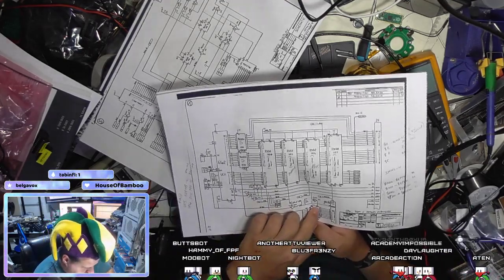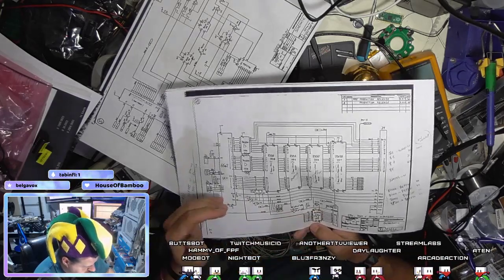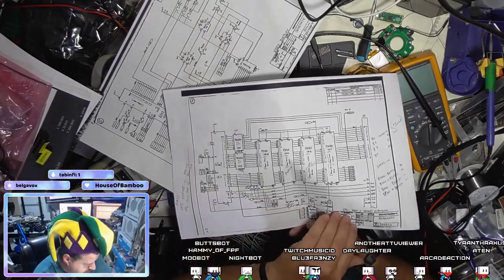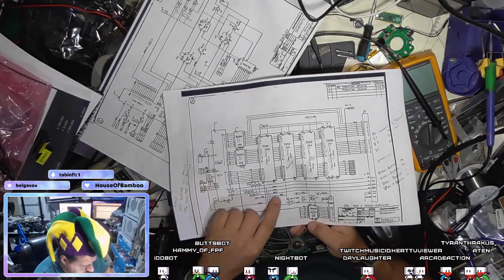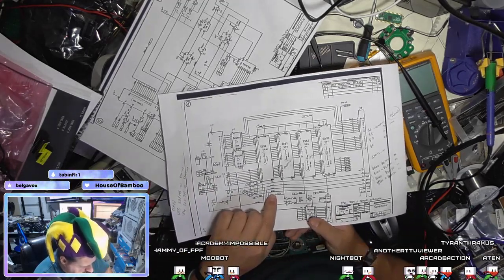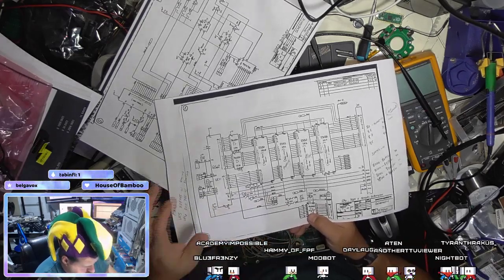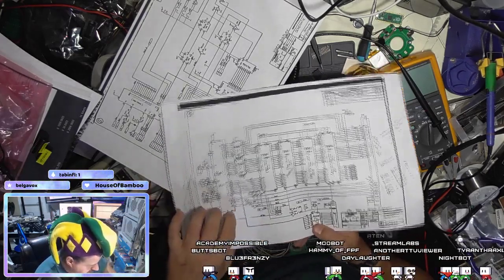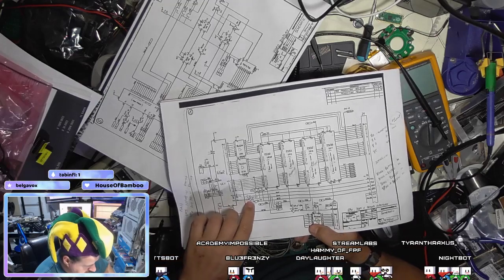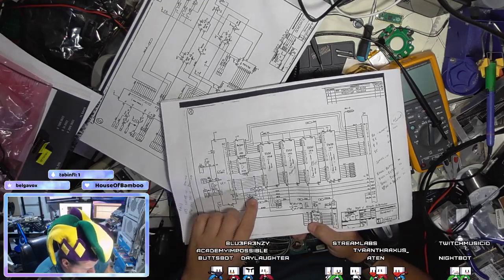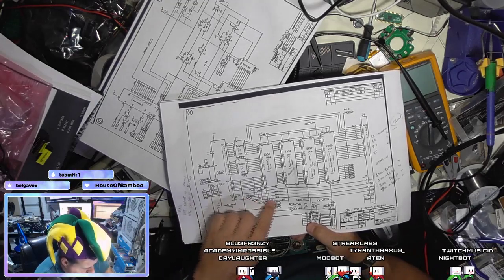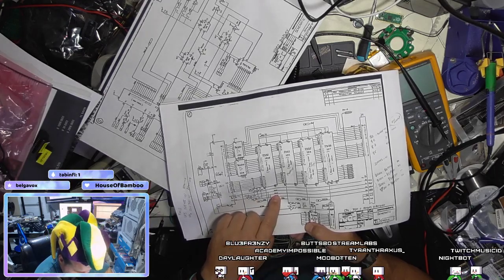There's a data direction pin, which controls whether it's being read or written, and that's usually driven off of the read-write, which again is buffered. There's the RW coming off the CPU. It goes through a not gate, sorry, an inverter, and it becomes a buffered read-write.